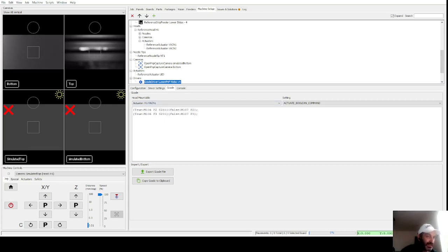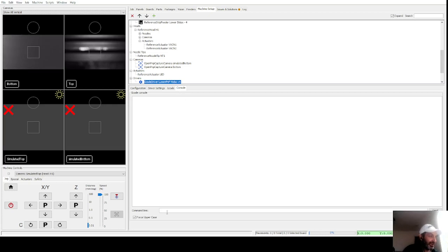And if you're really excited about this sort of thing, you can actually go in, and we have M106 P2 S255. We can go right here, M106 P2 S255, and we've got the pump running full speed. If we do 128, which we're not really going to do, the pump starts running weirdly. And if we do M107, we put that pump out of its misery and stop it. I'm sure you could hear that. I hope you could.